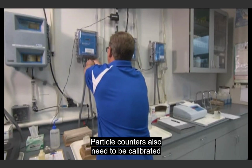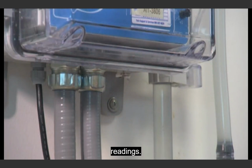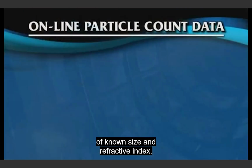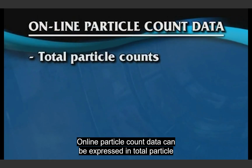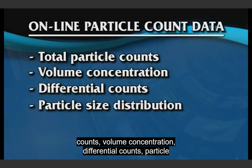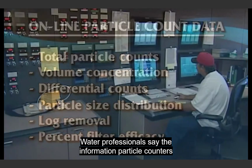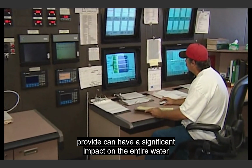Particle counters also need to be calibrated so sensors will provide accurate particle size and shape readings. This is done by using calibration spheres of known size and refractive index. Online particle count data can be expressed in total particle counts, volume concentration, differential counts, particle size distribution, log removal, and percent filter efficacy.